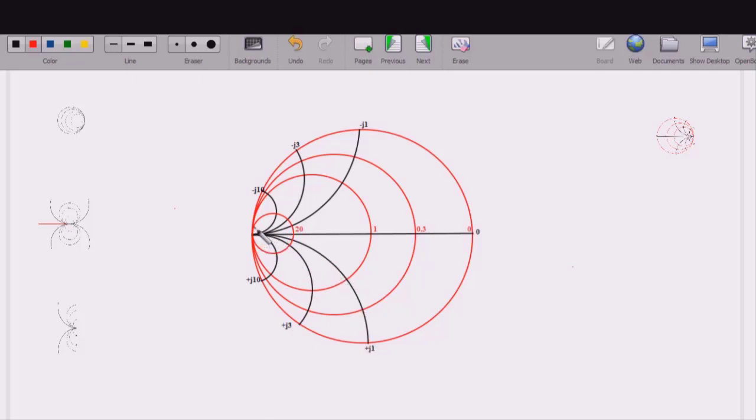So if you are going to represent a susceptance of 0 mho, then you need to work on a circle whose radius is infinite. So it is this circle actually, because we are drawing only the small part of that circle whose radius is infinite. It is going to appear as a straight line. So this horizontal straight line once again represents the reactive component. Here it is susceptance. Okay, and the concept is once again the same.